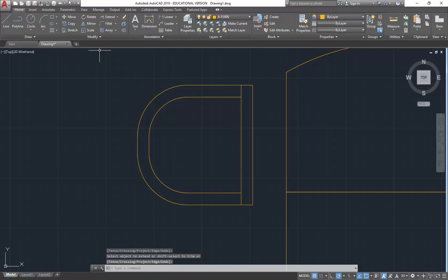So I'll just repeat that because that's just worth looking at. So again, extend, and then enter before you select anything. Then click on the line that you want to extend, which is this one, and you need to click both ends to extend the top and the bottom. And then, now having said all of that, there's a step they... Oh no, I see what they're doing. Okay, now it all makes sense to me.